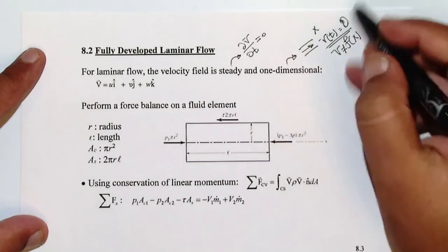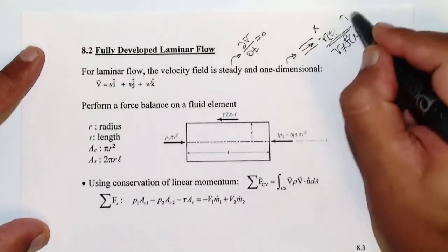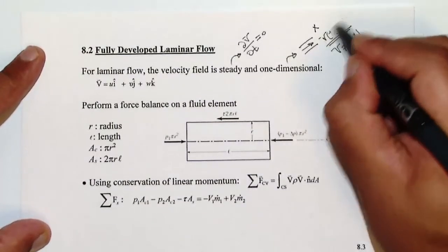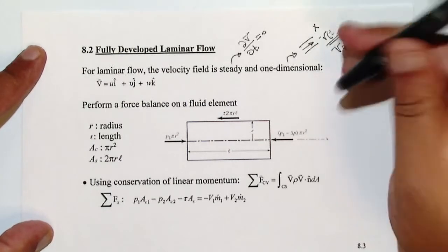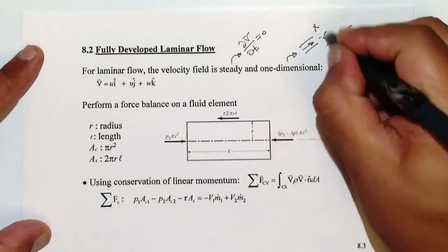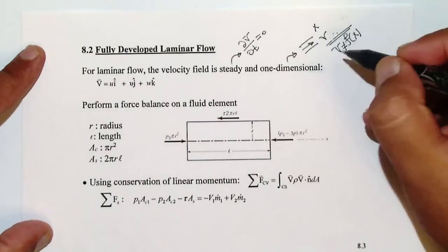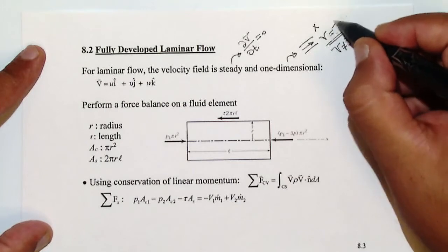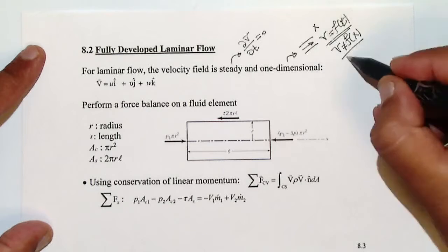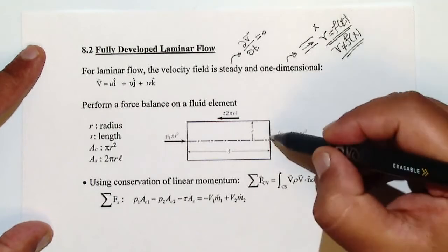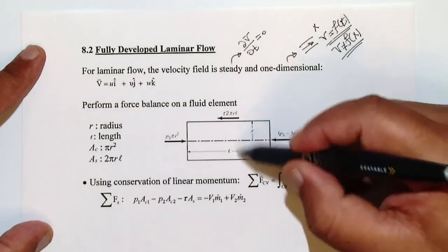Okay, so both of them have to be set as an assumption here. That's a true assumption: the velocity is not a function of t and not a function of x. And also for y it has to be r, and also for theta. So v is not a function of r, t, time, or x. And if that's your pipe, it's going to change by r, but it's not changing over theta.